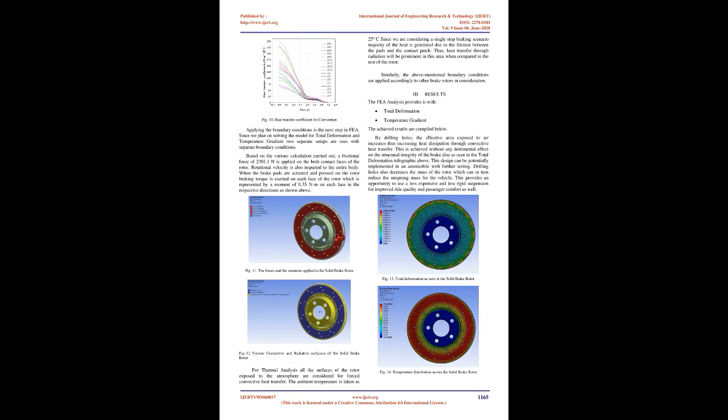Using the below Figure 5, mesh parameters: 176,237 tetrahedral elements and 280,626 nodes are created. The Delaunay method, which is employed by ANSYS CFD tetra mesher, is robust and fast. In addition, the advancing front method has the ability to generate a smoothly transitioning tetra mesh with a controlled volume growth ratio. Similarly, using the previous Fig 7.